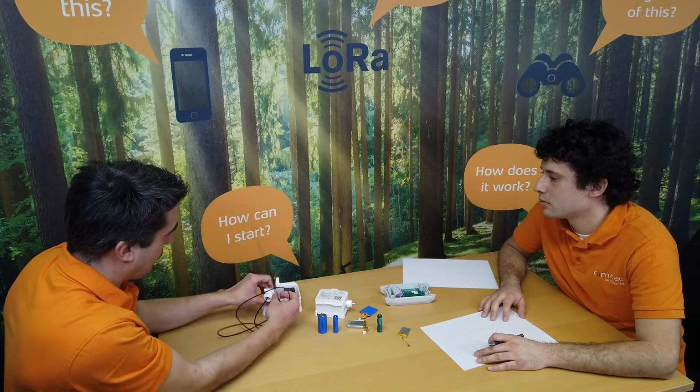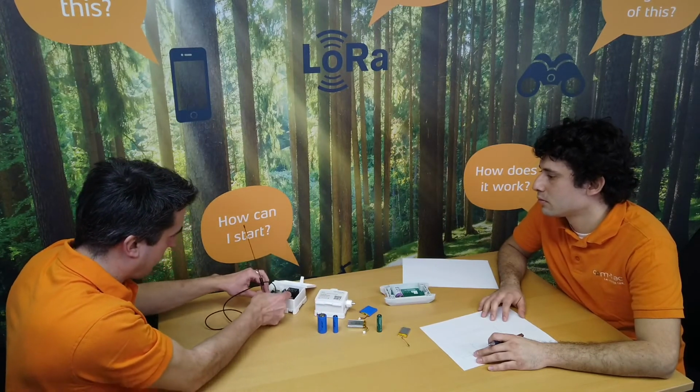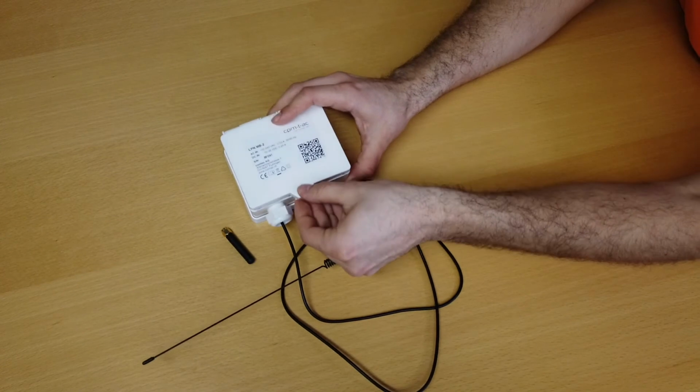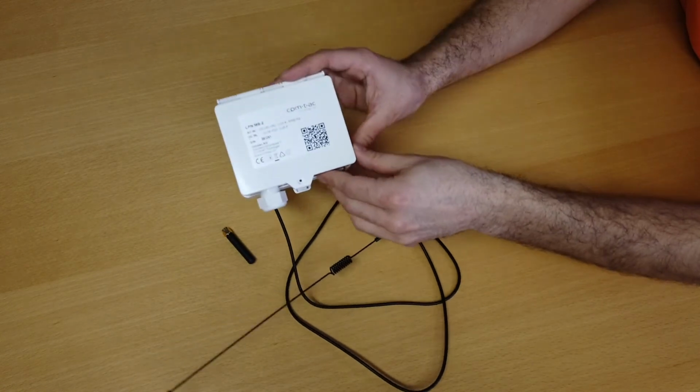Another key point of a LoRaWAN sensor, in particular of our sensor, is the antenna which is included on it. To boost the antenna performance of your device, it is important to keep the antenna in mind during the whole design process. Don't just leave the antenna aside and place it at the end. Integrate it from the beginning and build your device around it.